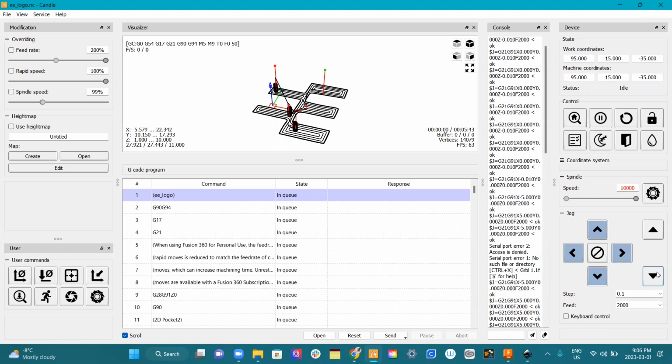I wiggle the piece of paper until it doesn't wiggle anymore. And I just keep clicking this because I can barely see it moving, but at some point my paper stops wiggling because it's being pinned, and then I know it's on the surface of the thing. That's it there pretty much. Yeah, I can't move it. So back it off one, take the piece of paper out, and I can see that it's just barely on the surface of it. So that's how I set up the thing.